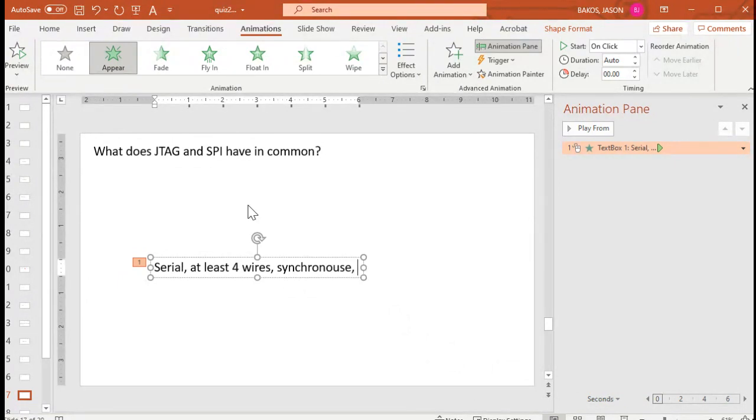They are not. Yeah, it's all of these. Shift registers. Sorry, I misspelled synchronous. They work by using shift. They shift bits. So you shift bits in, you shift bits out. You shift bits into the slave, shift bits out into the master.